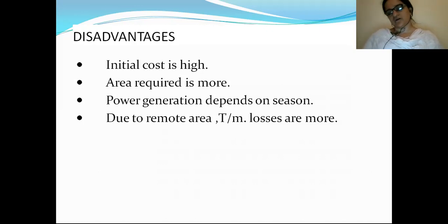Why? Because we have a sufficient number of nuclear reserves and coal reserves in our country. As we have sufficient fuel in the country, advanced storage of fuel will be done in the storage unit of the power plant, and based on the load requirements, the operation will be done and electricity will be generated. So thermal and nuclear power plants can be used as base load power plants, whereas a hydroelectric power station can only be used as a peak load power plant.